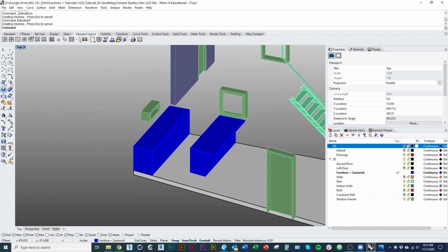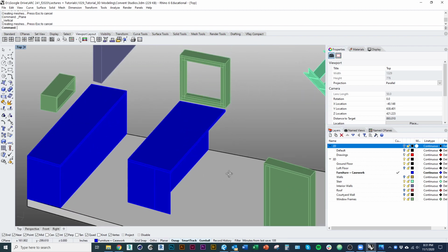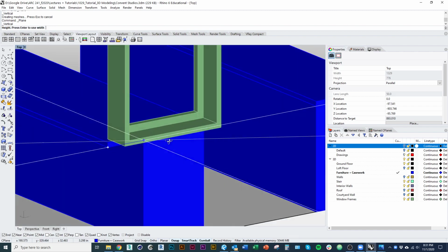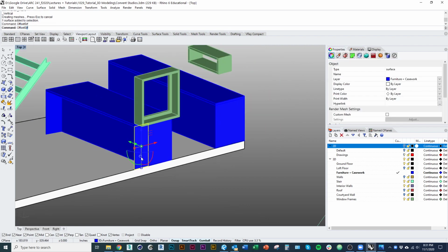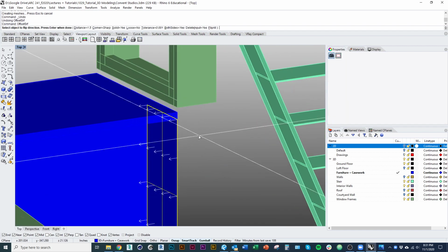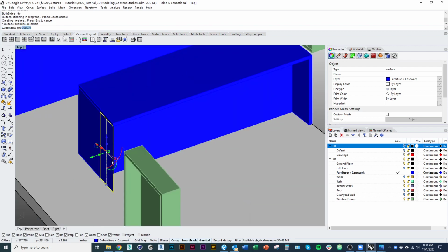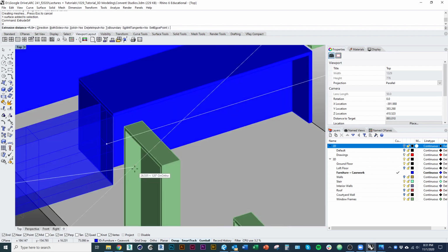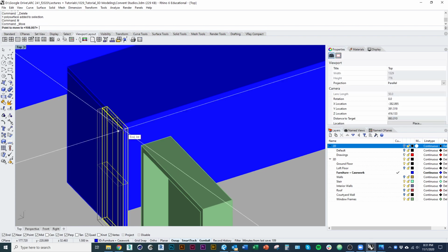I'm going to make a plane, do that little end piece of my cabinet here. And then I'm going to offset surf to give it the thickness it's supposed to have. Not meant to do that both sides. There we go. This one I'm actually going to extrude. That way I can go in plane with my weird angled cabinets. Move that over.